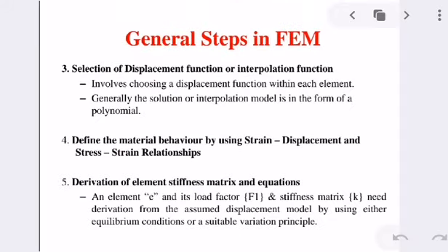And after numbering of nodes and elements, we will select the displacement function, which involves choosing a displacement function within each element. And generally the solution or interpolation model is in the form of a polynomial. And after selecting the displacement function, by using the strain displacement relationship